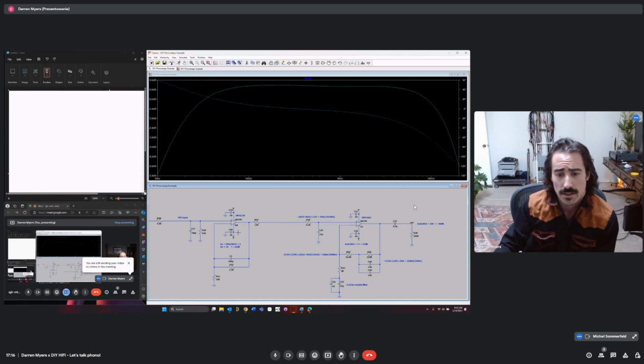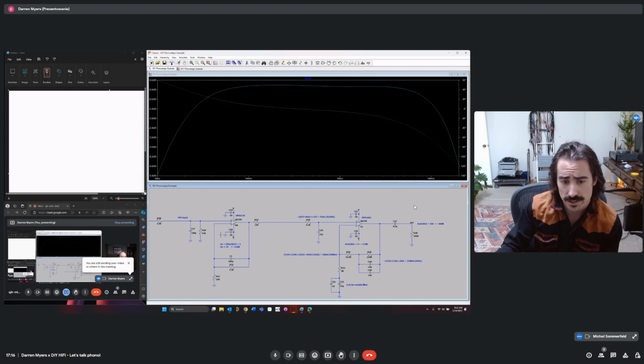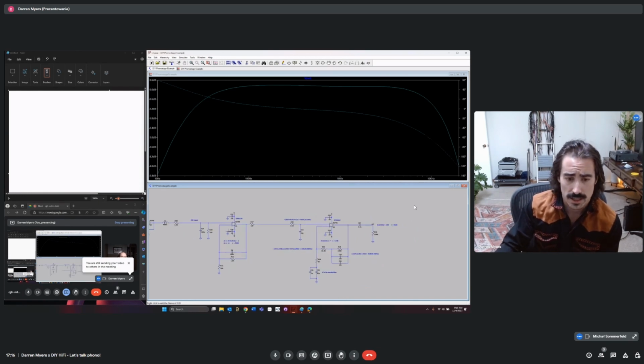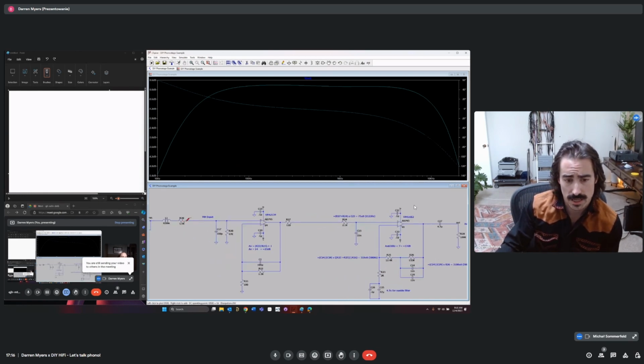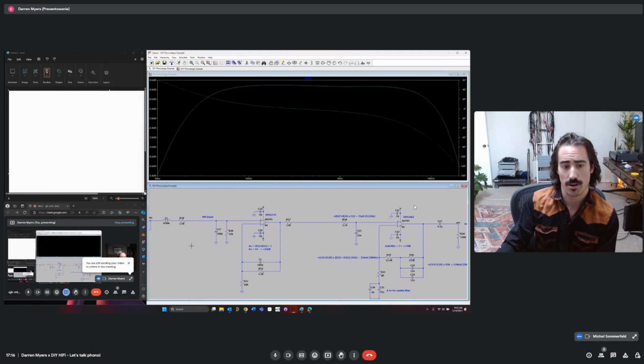And so for this stage where we're coming from a cartridge, if you look at the impedance going into the cartridge, which is simulated with L1 and R38, it is not very low. It is somewhat high. It's significant source impedance.